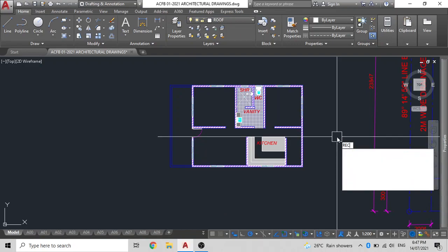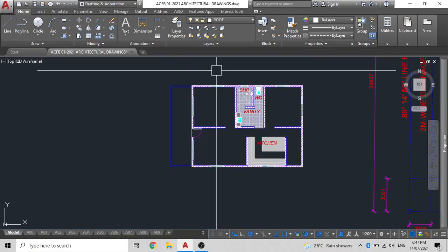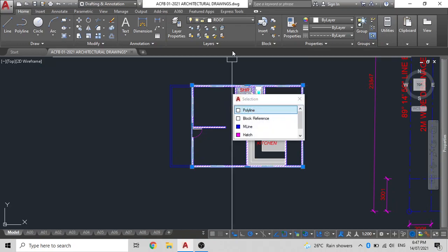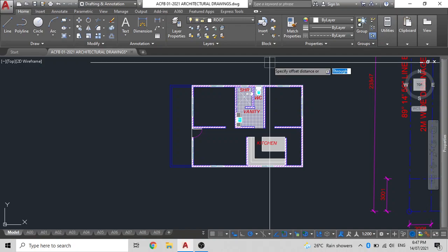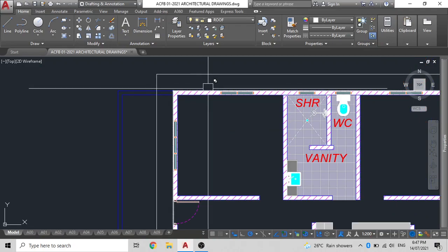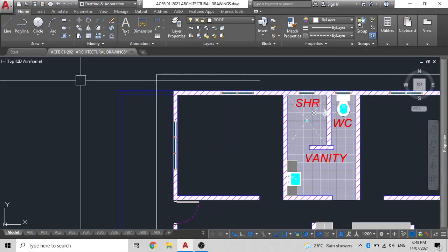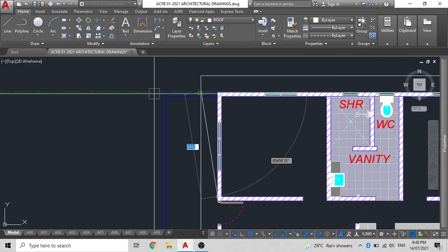So we'll just simply draw a rectangle. We'll draw two rectangles actually, and we'll just offset them. I usually like to use a distance of 600 mm offset, because you can also use a sheet of board and divide it into two, so you get 4.8 meters of eave cladding as well. So you don't have to cut and waste that much piece of board. Every measurement that I take in my drawings is conservative of the materials, and they are slightly less expensive than the standard ones.